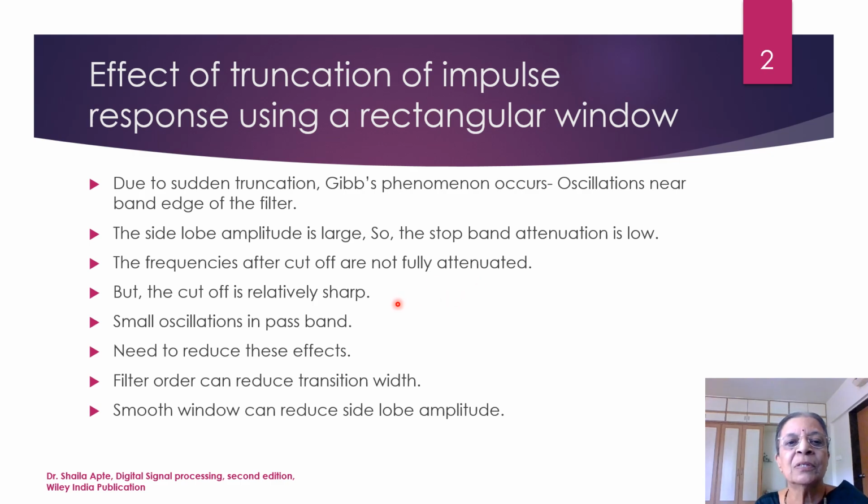The cutoff is relatively sharp, in the sense that the transition width is relatively okay. But the side lobe amplitude is large. There are small oscillations also in the passband. So we need to reduce all these effects. So we want to improve on this design.